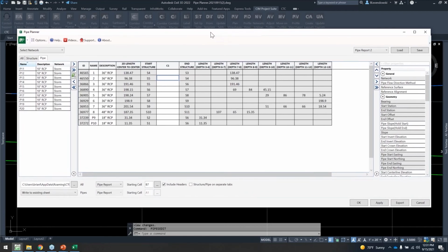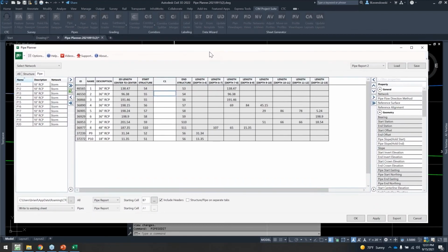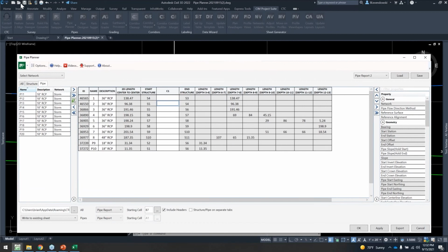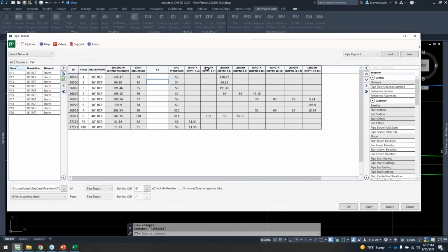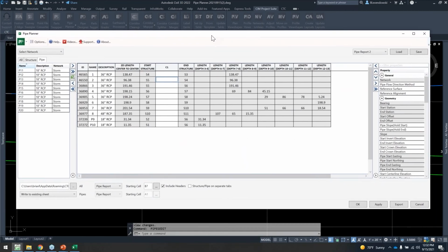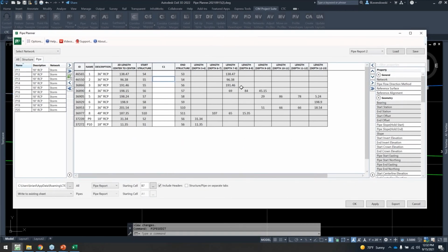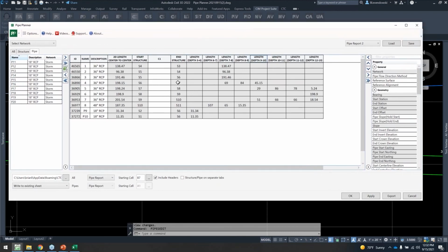Question about undo and redo within a tool, much like the undo command in Civil 3D. So there isn't an undo or redo right in here. And let me explain a little bit. If you added a property, for example, and you wanted to remove it, you can simply do that, right? Remove column. Same with parts, okay? The point I want to make is that everything we're working on right here is I bring properties in and parts in. We're not writing anything to the drawing.